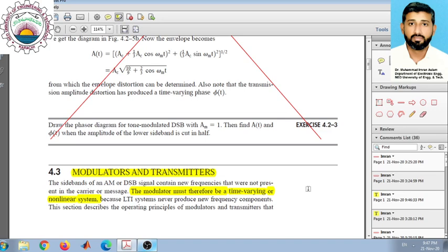However, when we look at the amplitude modulated signal, if you recall the frequency spectrum of the modulated signal, we notice that there are a few frequencies which are not available in the original signal. Like if a signal has a carrier frequency represented by Fc and a modulating signal with frequency Fa, in that case the output would contain three frequencies: Fc, Fc plus Fa, Fc minus Fa. In other words, the output would contain three components, namely carrier, upper sideband and lower sideband.